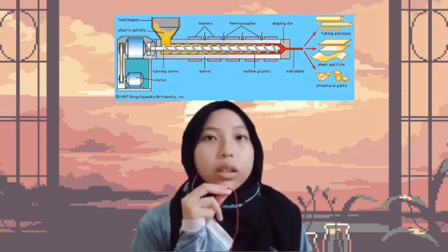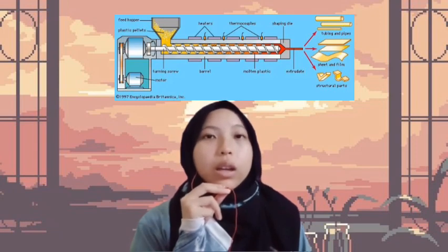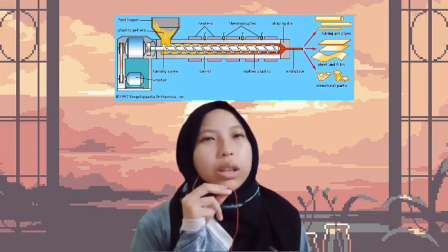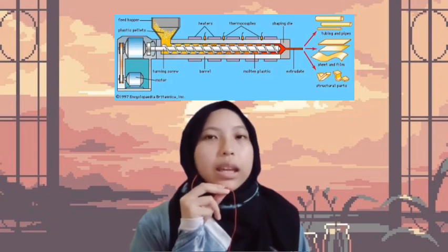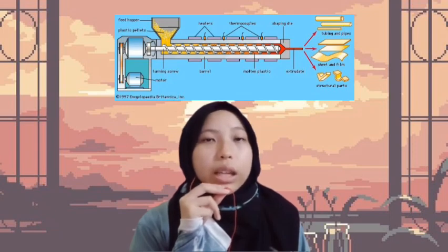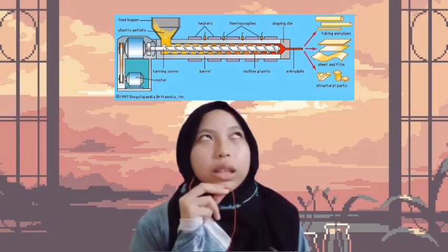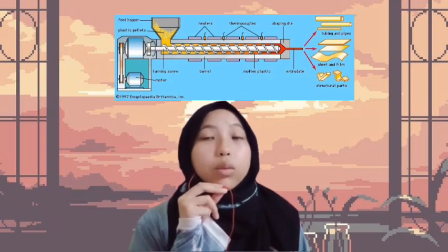The melt flow rate, which is MFR, for virgin was calculated to be 20 grams per 10 minutes, and that for 100% recycled polypropylene was 40 grams per 10 minutes. This wide difference between the MFR of the virgin material and 100% recycled PP occurs as a result of the presence of plasticizers in the recycled material and a small effect of degradation of the material.